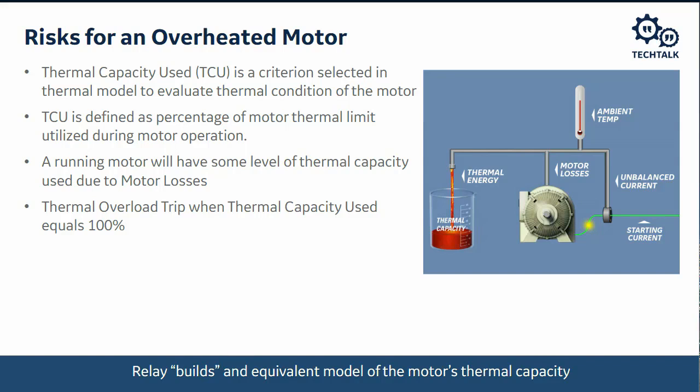Now, the presentation that was previously done, and it's available, that Christine Kreitz did, was about how you can restart that motor after you've had a trip, and how the relay models how that thermal capacity used decays over time and has to decay to a value that the relay will allow a restart. And that's a great presentation. I highly recommend that you view that presentation to understand how the motor thermal model cooling is basically calculated.